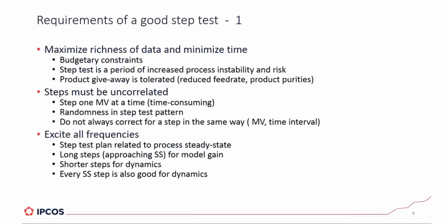What are the requirements of a good step test? Firstly, we would like to maximize the richness of our data, and then of course we would always like to minimize the time in which we acquire that. That is usually because of budgetary constraints on our projects.